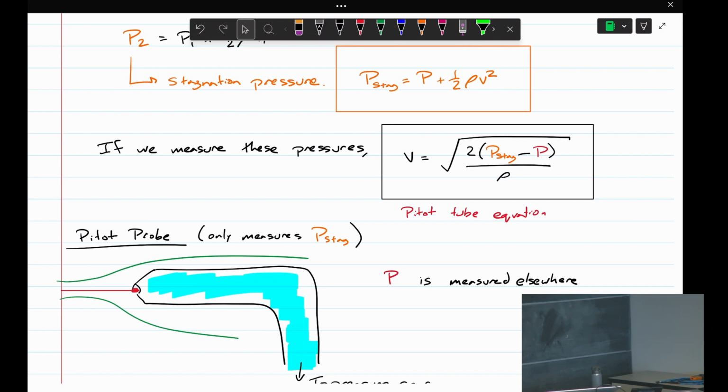The thing I was just talking about is called vortex-induced vibration. Remember we saw the vortex shedding behind a very big bluff body. The vortices are shed like that, so that's a sinusoidal force. That can cause structural resonance with the thing that's causing the shedding, which causes a lot of mechanical vibrations, and that's a big problem. So usually they're quite thin, because that makes their natural frequency much different than a typical vortex shedding frequency at that size.